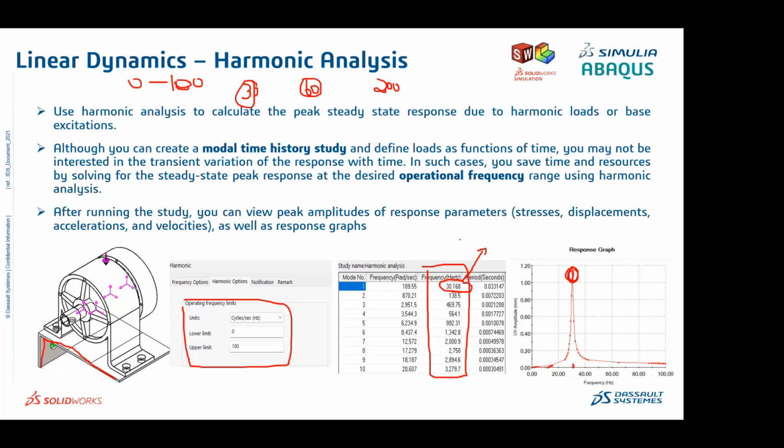So this is how you perform a harmonic analysis. To perform a harmonic analysis, first you perform a static analysis, then you make sure that your model is safe, then you perform a frequency analysis to understand the modes. I will also show how many frequencies you have to take for any dynamic simulation when I do it in the software. Once you take out the natural frequencies, right, then either you will be performing a time history analysis